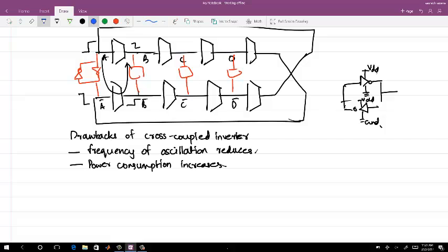So let's not put any. Ideally, what do we want? Let me put it this way. If I take this node, and we know that the bottom one is complementary, I can do this. A gain block which doesn't consume any power, which feeds forward the signal. The simplest one would be this. It adds a zero in the path.